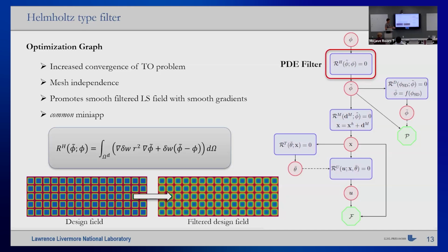If we don't have the resolution in the analysis mesh, we can't represent something. So if we can control the feature size in a weak sense and guarantee that the analysis mesh is fine enough, that's a nice thing. And there is a PDE solver like this somewhere in the miniapps common folder, so it's basically ready to use.